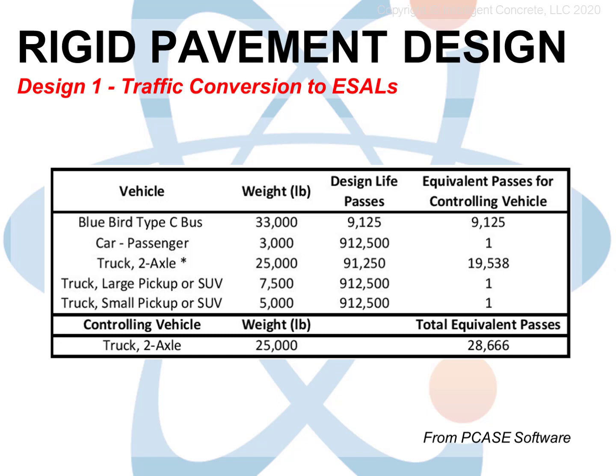You've all seen those black rubber hoses crossing roadways, usually hooked into a box, chained to a post or a guardrail. These are traffic counters. They used to be very simple, and each bump measured was counted as an axle passing over that point. A person would be assigned to sit there with a clipboard and take notes about the vehicle mix and estimated speeds. Nowadays, the traffic counters can estimate weight based on how hard the rubber hose is depressed. They can measure speed, they can measure multiple lanes at once, and many other functions.